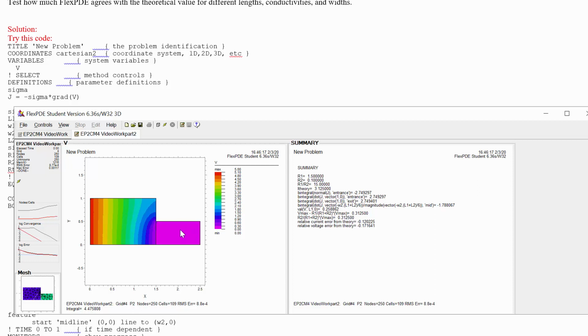It's got 15 times more resistance, so this is really limiting things. We actually get, I would expect, less current than theory. Let's check if that's the case. So I theory is 3.1, and we actually get a little bit less. So the reason for that is the theoretical calculation is saying that we can conduct all the way across the top, use all of the width all the way, and then when we get to here, no problem, we can just continue conducting in here. But actually, we can't do that. We have got to flow down through this and then across. This one doesn't connect to the other one perfectly.